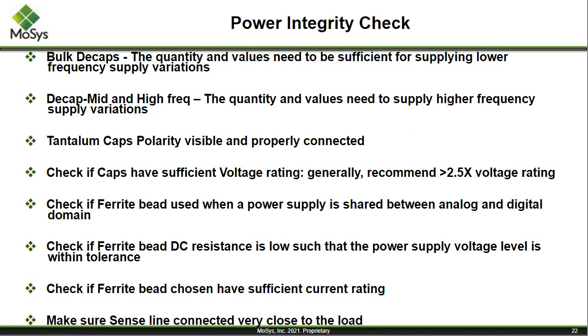The bulk caps, so you'll do bulk, you'll do tantalum, you'll do large capacitors. And again, those tend to be a little further away, but their frequency response is not as high usually. You don't have to deliver very high frequency response off of a tantalum cap, let's say. So the distance from the source is sometimes not as critical to where you place those caps.